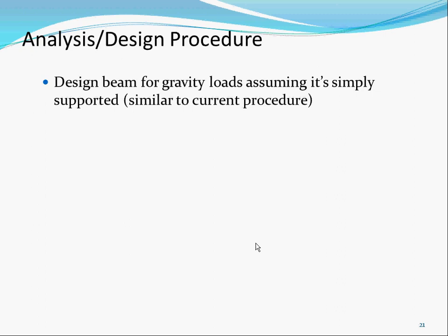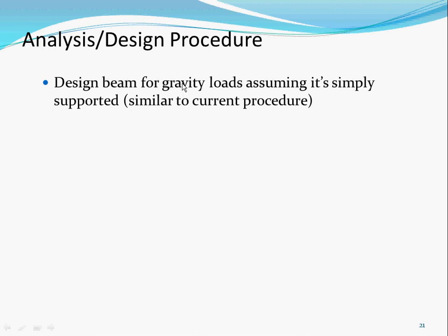Let's say you want to remove the link on the column bottom, and you have to shore it up. For us, if the beam is actually taking out the gravity load, you can take out a link at the column bottom and leave it whatever it is without having to shore. Then just add the link to the column bottom, and you're good to go, because you designed your beam for the gravity load as a simple beam already. When we go to SAP and the Excel sheet, I'll tell you what step that is and how we're doing it. But the first thing is we are designing the beam for gravity load, not lateral, just the gravity load, assuming it's pinned, assuming there's no moment contribution.